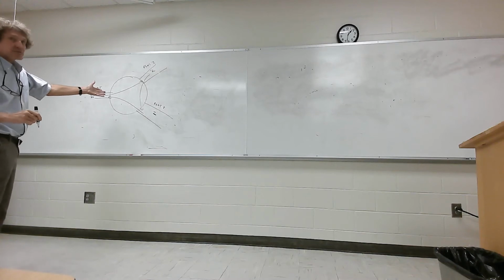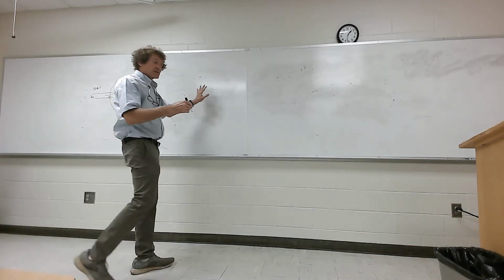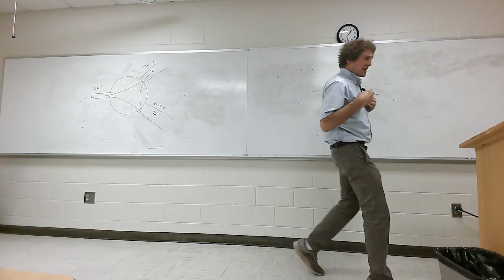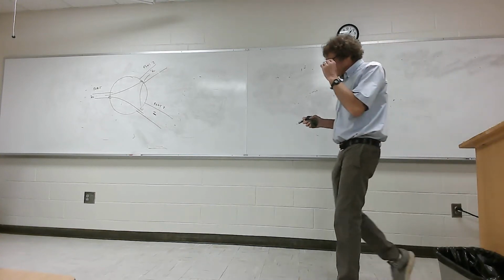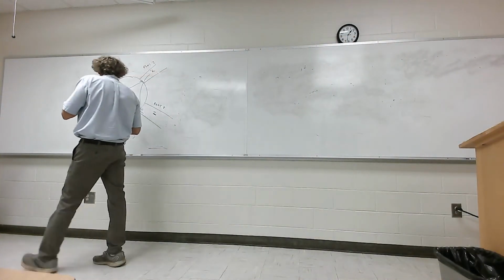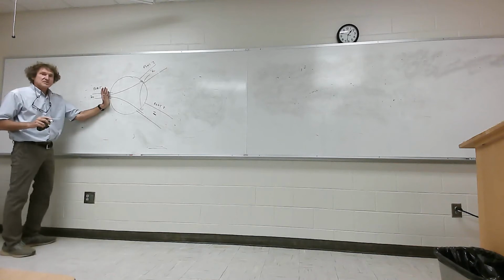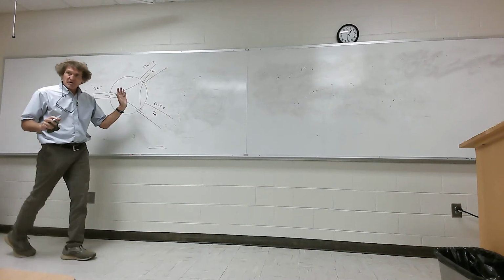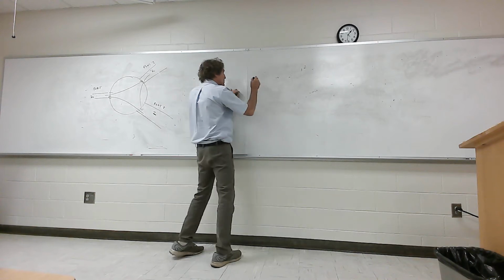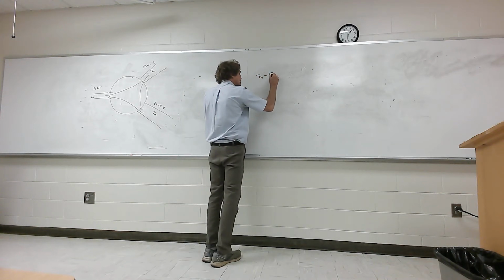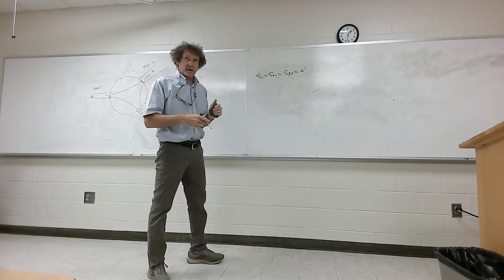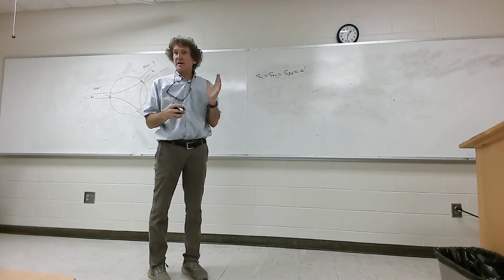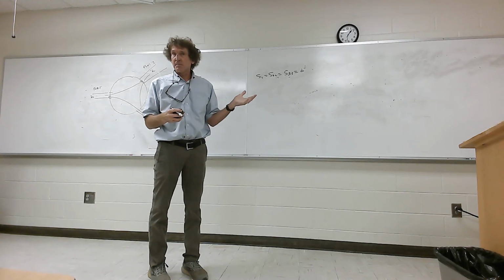So now we need the S parameters for this. Let's start by doing it this way. He'll show you the basic diagram of that. But here's what the ideal is. They want all these ports matched, so they want the reflection coefficients on all of them to be 0. Y'all understand that? So S11 equals S22 equals S33 equals 0. They don't want anything reflected. If it was reflected, you already lost energy there.